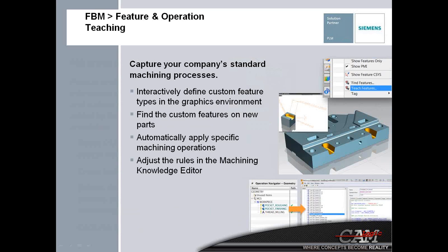The beauty behind the feature-based machining with NXCAM is that it comes with what we also call a teach mode. It can interactively define custom feature types, and the nice thing is it's a graphics interface environment, so you don't have to know programming language or code in order to modify or change the machining library, define custom features, and automatically apply specific machining operations, and again, adjust the rules inside the Machining Knowledge editor.